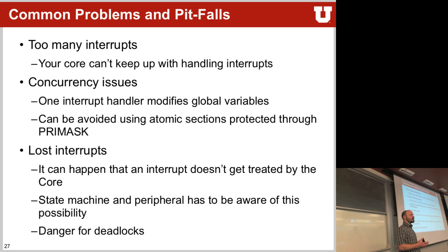If your global variable is stored somewhere in memory, remember what happens if you add 1 to a global variable? Well, you first load the value into a register, increment the register, and write it back. So what happens if we loaded the register, we go into the interrupt service routine, the ISR now modifies that same memory location, we come back into the original code, and we now store that old value back into that global variable? You just completely ignore whatever the ISR did on this global variable because you wrote it right back. This is what's called concurrency.